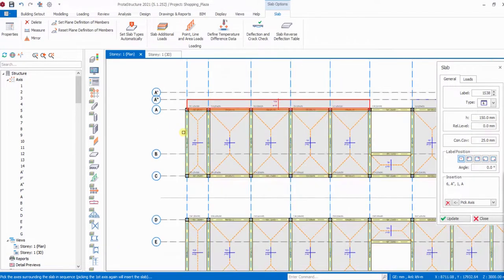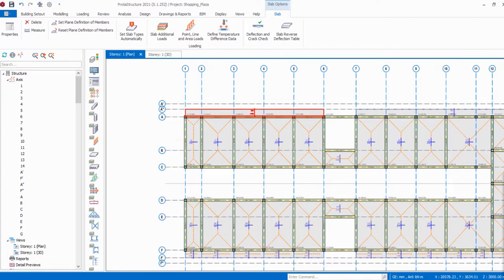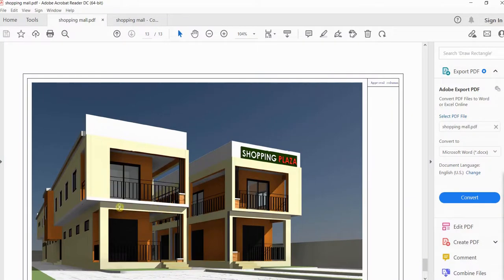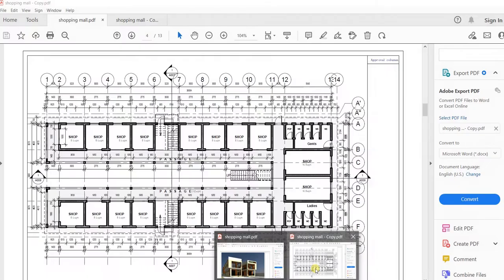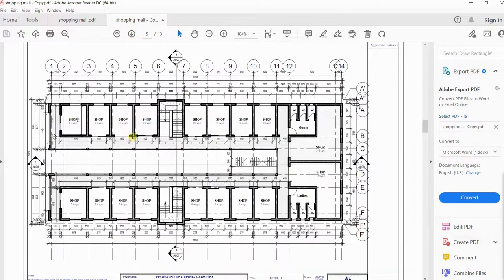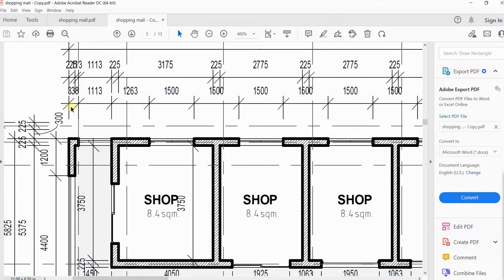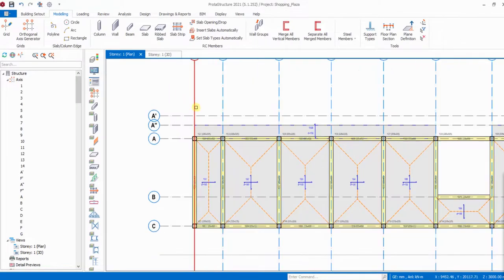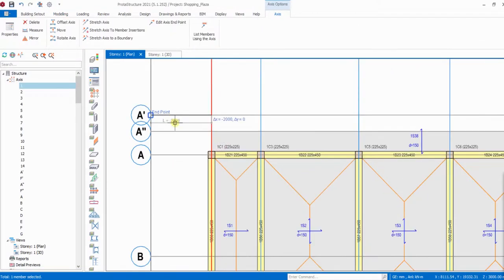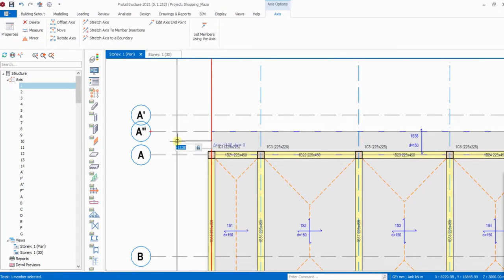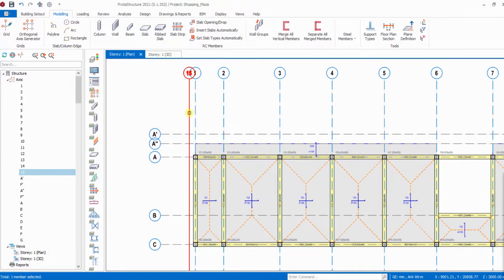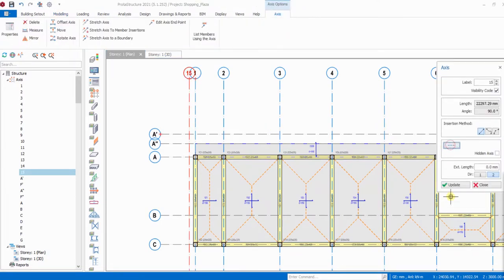So we've done that. But there's also another small cantilever at the front here. So we still need to give that cantilever. For this, you can see, you extend a little. And what is that width? From here to this 3380. So let me just make it 350. So let's assume 350 cantilever there. So here I'll right click this, offset, shift F2, minus 350. So I've created that. Make it a construction grid, and update.